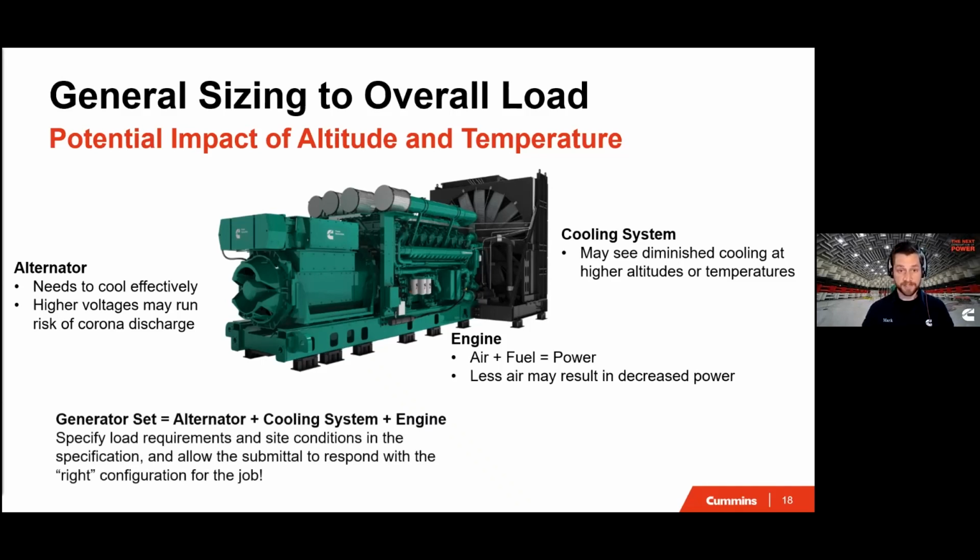So with all that being said, I share all of this not to make you worry about all these details, but for your own awareness to help you keep the submittal response to your specification honest. If you've ever run through sizing software and saw numerous entries for a single generator set model, usually that's because the sizing software is offering different models of cooling systems or different models of alternators for your consideration as well.